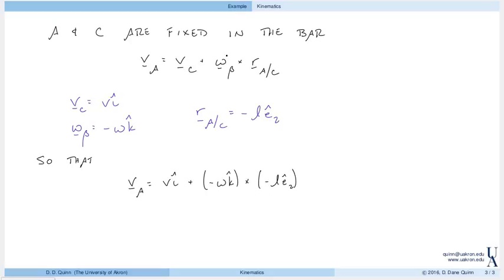And I do want to point out that this is the angular velocity of the bar, given as omega of the bar, and it's a vector, while in this representation, omega is the angular speed. I realize they have the same symbol, Greek letter omega, but this one's a vector and this one's a scalar, so they're actually two different things. They're closely related, obviously, but there is a subtle difference between the angular speed and the angular velocity.